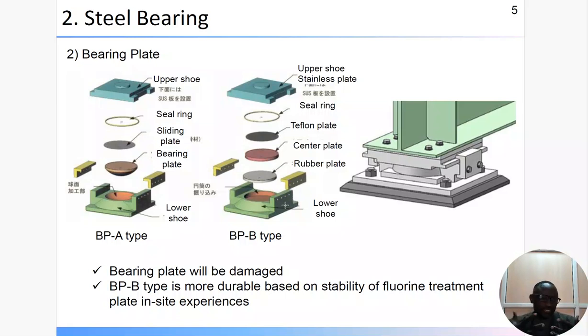If it is 15 years, 20 years, definitely now you know either they can replace this other element or the entire unit can be replaced. So most bridge bearings do have about 15 to 20 year maintenance-free life, beyond which it becomes a bit risky to accommodate loads that are ever increasing while the condition is deteriorating.